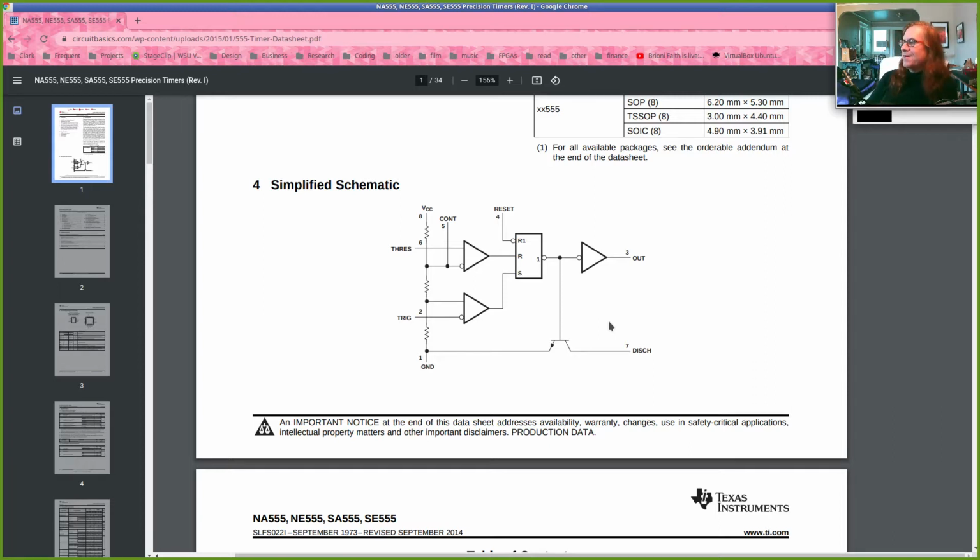And if you build a 555 circuit and you hit it with compressed air to cool it down, you'll usually see a change in the timing waveform. If you heat it up, you'll see another change. If the power supply changes, the frequency may change a little bit. It's not super stable, whereas if it had a crystal inside, it would be using the resonance of some material like quartz to lock in a particular frequency of oscillation. So this is using what's generally called an RC circuit.